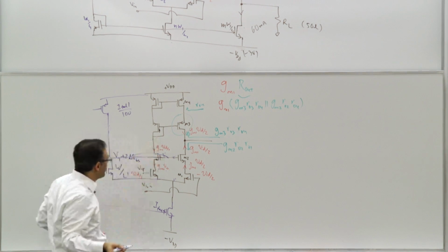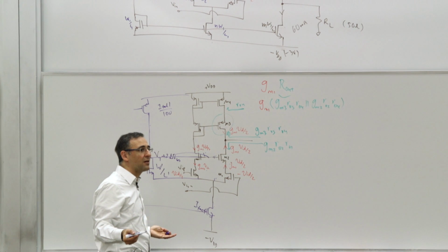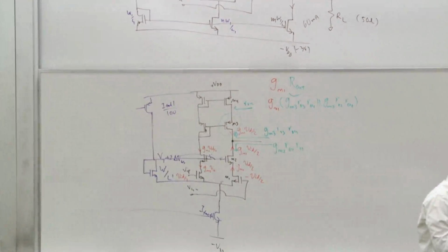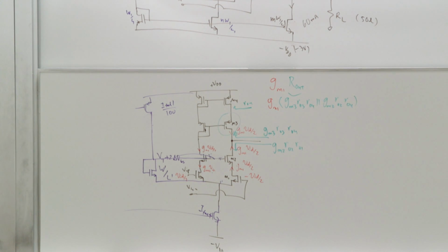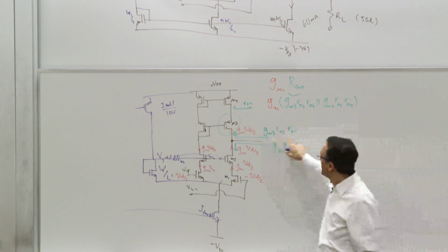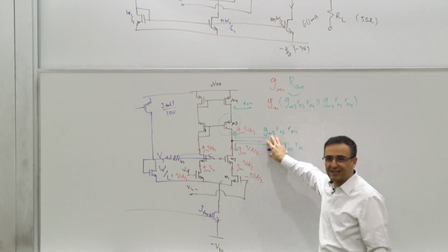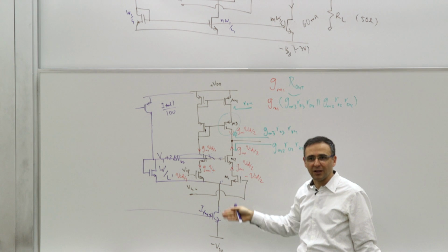Now, is this an OpAmp? Yeah, it's an OpAmp with a gain of 5,000 as long as the load is not resistive. You put a load of 50 ohm there. What's the gain? Again, 0.2. So you want to definitely make sure that if you apply a resistive load, there's something in between. Otherwise, you've wasted all the effort that you put into making something like that.